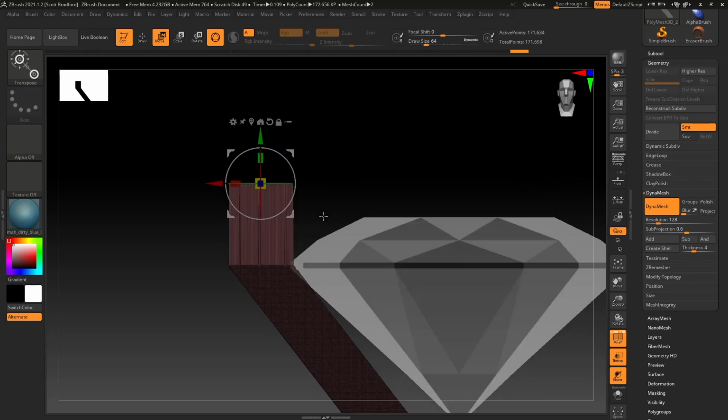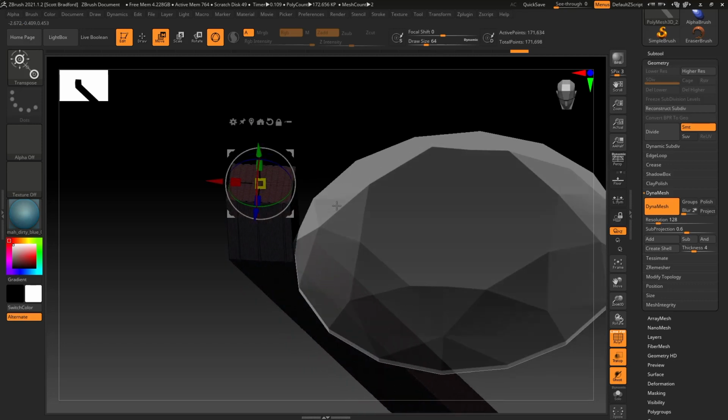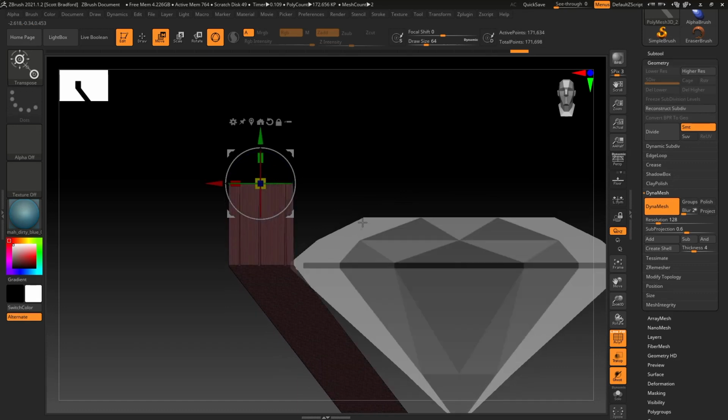When you extrude these out, the prong is probably going to come around 40, 50, 60% up the stone. That's relatively normal depending on the type of setting you're doing, probably closer to about 40 or 50%. I always say it's better to have a bit too much metal on top of the prong than too little, because the person setting it can always bring down the height of this prong, or after it's set, actually shape the prong on top of the stone to make it look the way they want to.